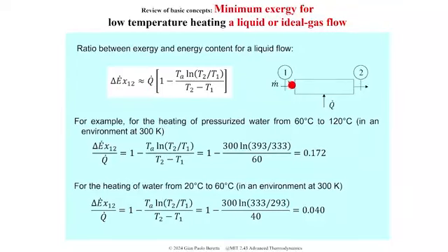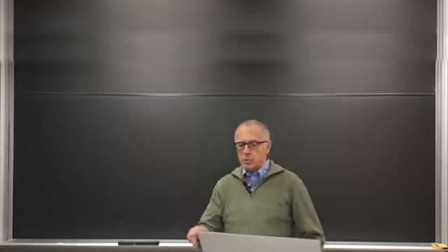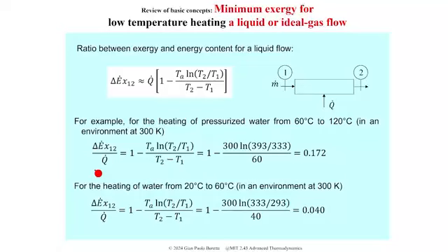So it's the exergy content of your heated water after you heat it. That's the exergy. And the exergy, remember, is the minimum work required to do that job. So this ratio, exergy change over heat, represents the minimum work per unit energy of your heating. And so that is useful. So it's the best you can do.